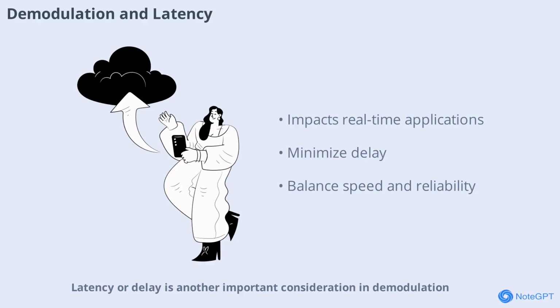Latency or delay is another important consideration in demodulation. Some techniques introduce more delay than others, which can impact real-time applications like voice calls or live streaming. Engineers must choose demodulation methods that minimize latency while still providing reliable data recovery, especially in time-sensitive systems.